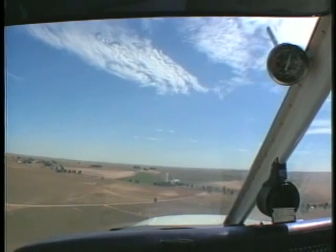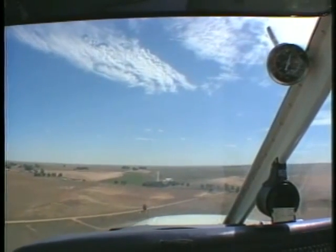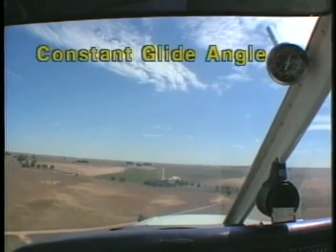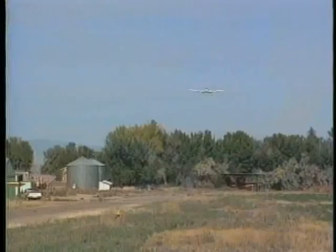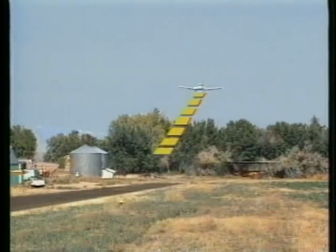All the while, progressively reduce airspeed to smoothly transition to the short field approach speed. Ideally, the final approach is conducted at a constant glide angle, airspeed, and power setting. The objective of the short field landing is to clear the obstacle, land safely, and stop the airplane with little or no floating. This requires precise control of airspeed and descent angle.